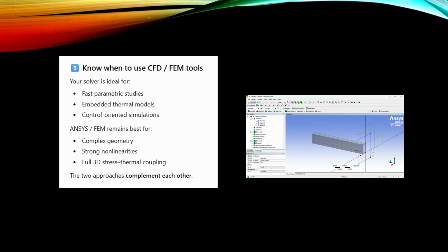If your slab is not a simple slab, for example if it has fins, I recommend you use CFD. But remember also that it's always good to compare results and not to trust CFD too much. For example, if you have a Python code and you have CFD, then you can compare those results and find out the reasons behind the differences.